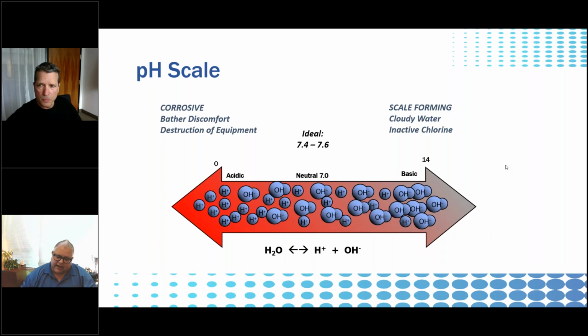But as the pH goes higher and higher, that hydrogen ion falls off of the hypochlorous acid, leaving behind a hypochlorite ion that doesn't do anything for you. So it's still chlorine, it's still in there, and you can attach the hydrogen back onto it and make it active. But ultimately, when that hydrogen ion is off and it's OCl, then your chlorine is not effective or efficient.